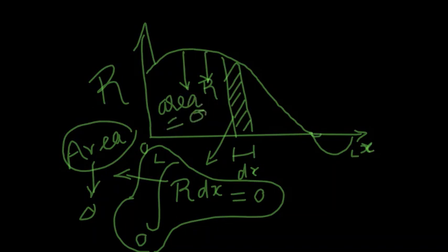This method should be superior to the point collocation method, because in point collocation you are making the error 0 only at chosen points. But in this method you are making the error 0 in an overall sense by making the area of the error curve 0. And this method, where you make the area 0, is called the subdomain collocation method.